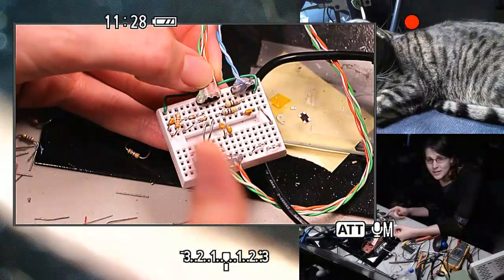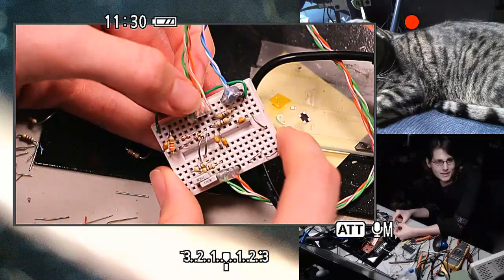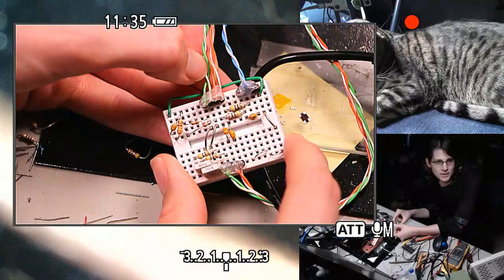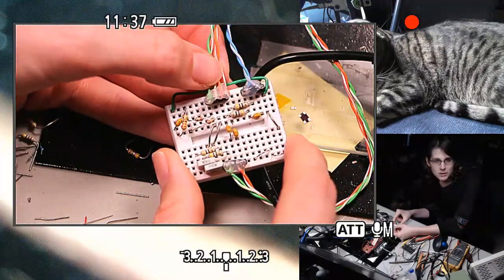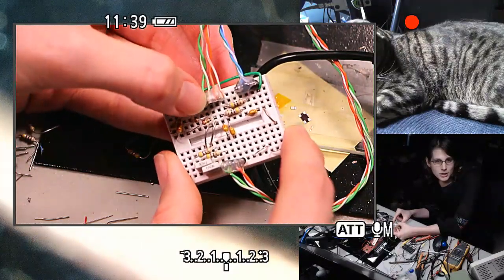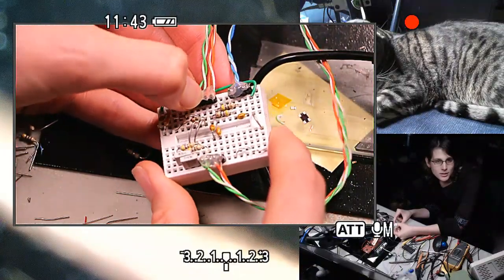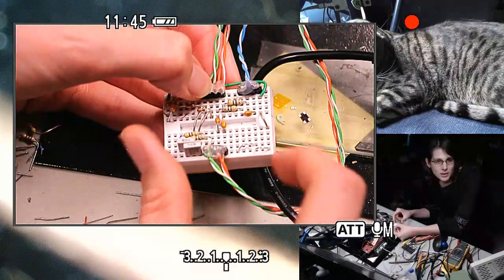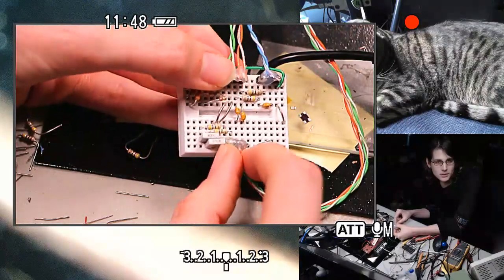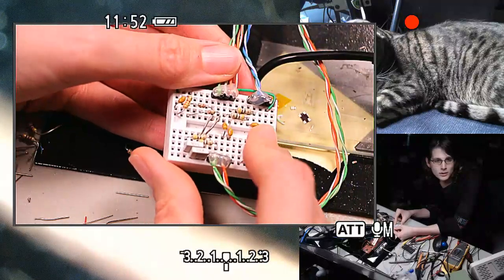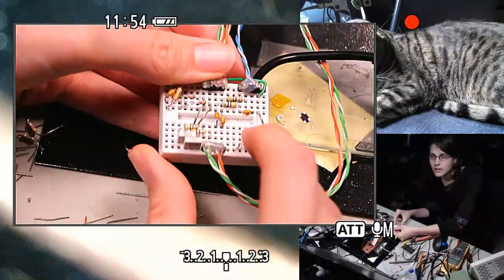So, that again could just be a problem with the PHY, something on the analog side of this. Or it could be something clocking related, and maybe there's some other timer on chip that is contributing to those pulses that I'm not changing, or maybe I'm introducing a bug somehow that's causing the pulses to not be a useful length. And again, that's not usually a problem, but it's borderline enough that it has me concerned.